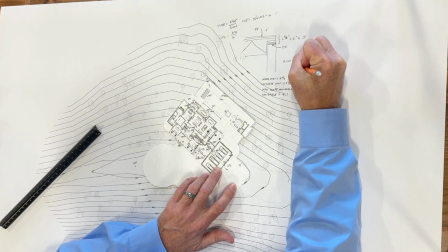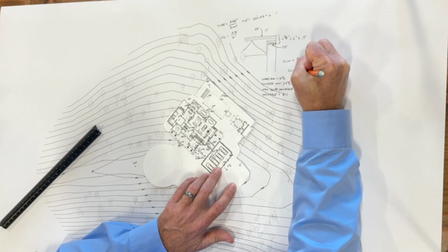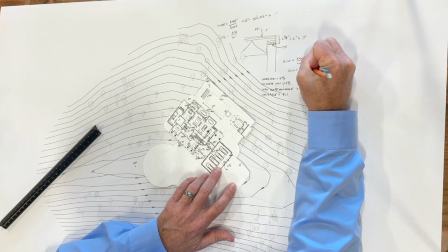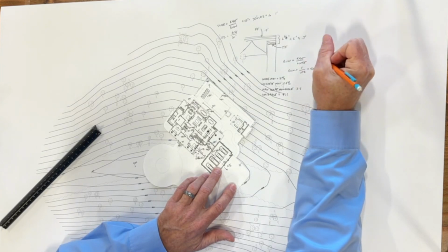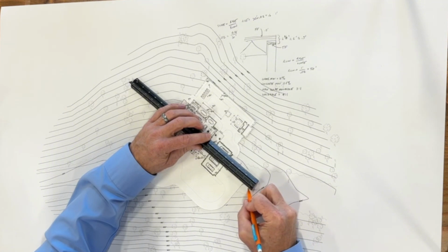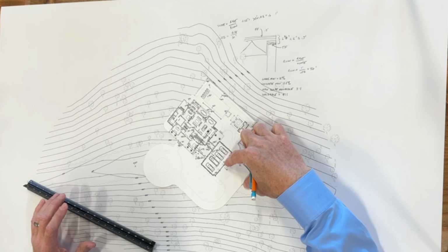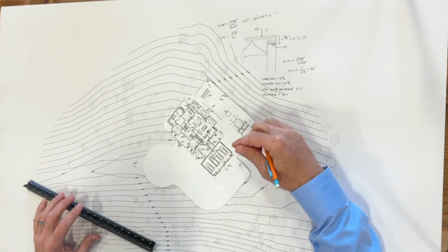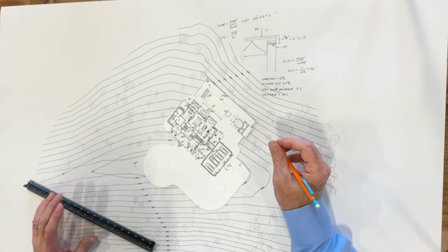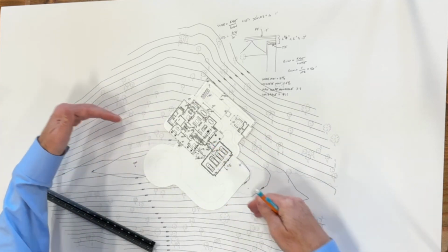So now what is that run? So it's 1 foot divided by 0.02. So what's that? I believe that's 50 feet, right? Pretty sure it's 50 feet. Yeah. So 50 feet, though, would be all the way out here, right, at a 20 scale. And to me, that's just like, wow, that's way out there, right? You know, to have it be that flat. And 2% is pretty flat. So we could make it that flat, but I don't know if we'd want to because you got to think about it. It's starting to go downhill.